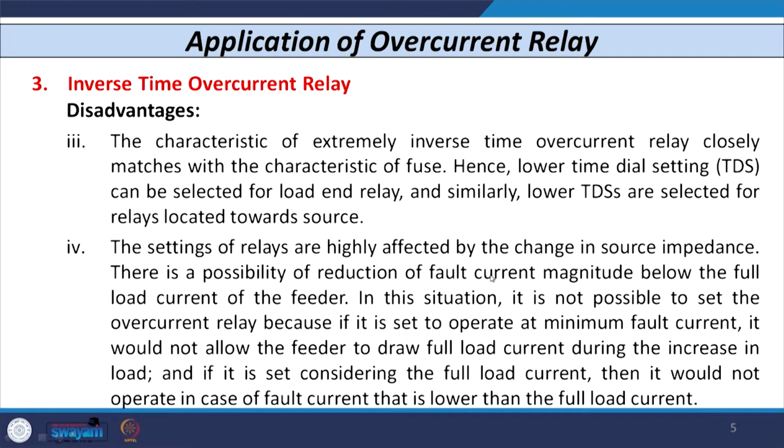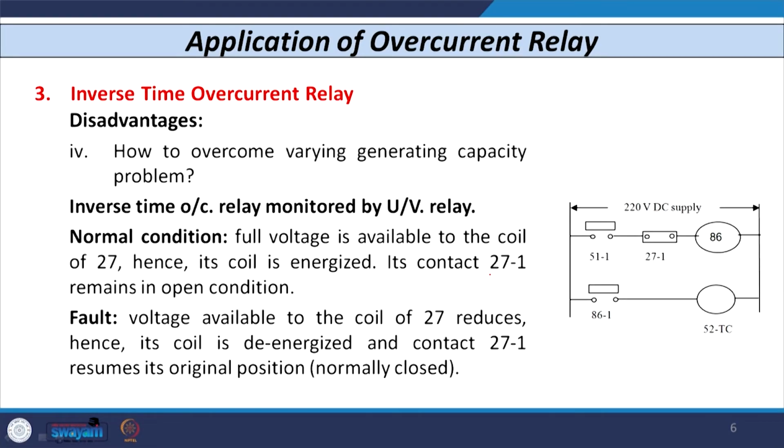So to avoid this, the solution is that we have to use an overcurrent relay that is monitored by an under voltage relay.